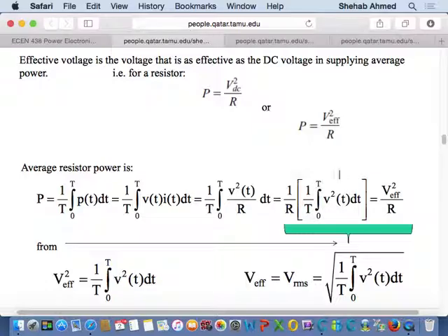with this term. This term is what? This term is the average value of this v squared waveform, right? It's 1 over the period times the integration over the period of some waveform. So they say that this v effective squared is basically what's between these brackets. And this v effective is what's equivalent to this DC voltage producing power through a resistor. All that is nice, definitions, etc.